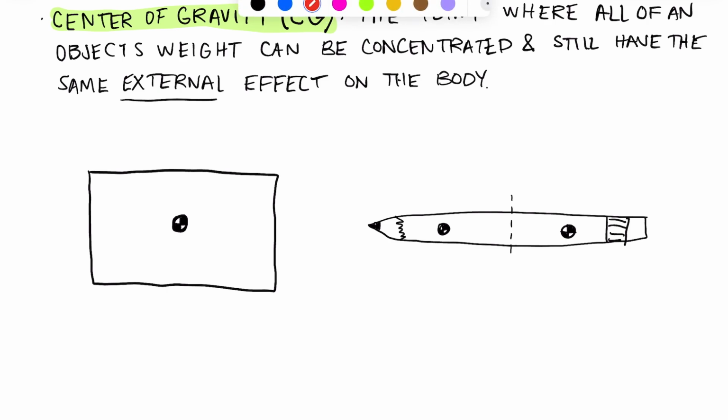We know that the weight of this first half is going to be, if I place my finger here where I've drawn my dotted line, trying to rotate me counterclockwise, right? Now the weight of the second half is going to be trying to rotate me clockwise about my finger. And so the goal is to place my finger, to place the support somewhere in between these 2 weights where the moments caused by each of them is perfectly balanced.